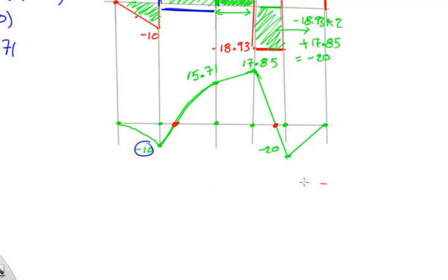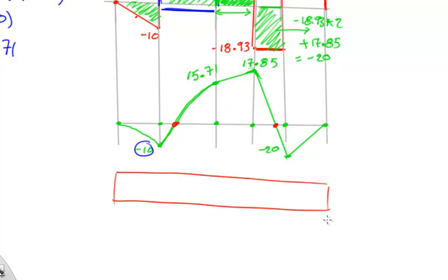So just a quick reminder, if this was concrete, where would you put the positive reinforcements, or the bottom reinforcement, and the negative reinforcements, or the top reinforcements? You need to find these two and say whatever's here is up and whatever is here is up, and for this I'll put the reinforcement in the bottom. But you need to know the distance. You're gonna tell the people at the site where to cut the rebars.